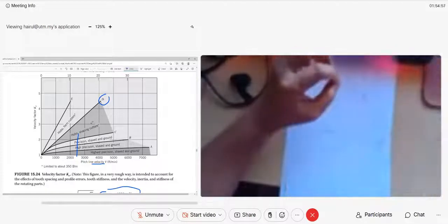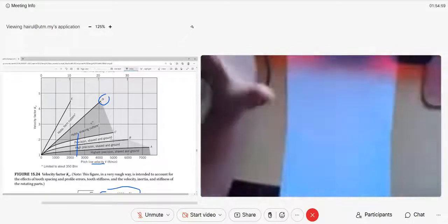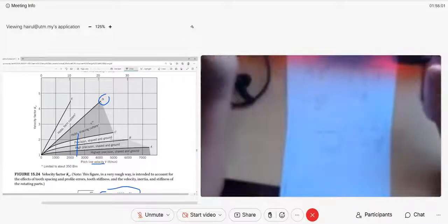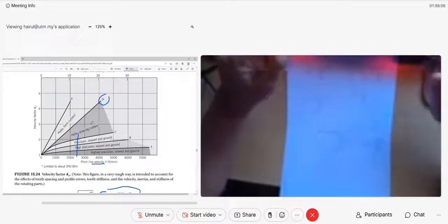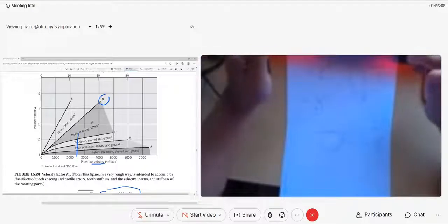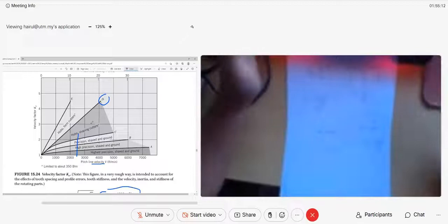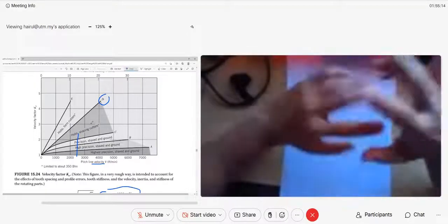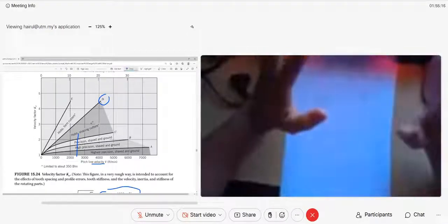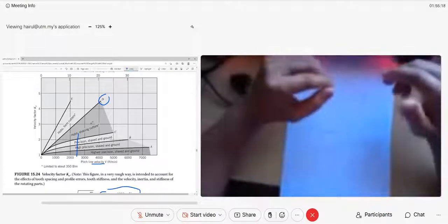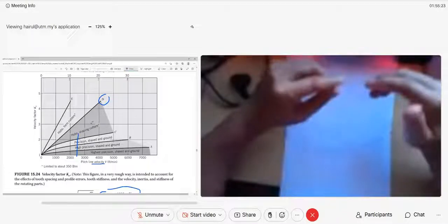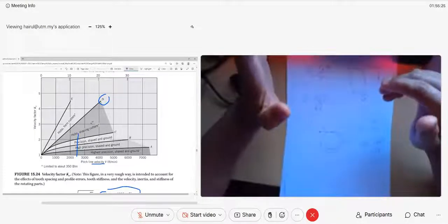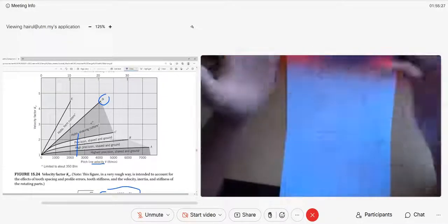Let's say you and your group assume that the drum of your foot mixer, for example the food technologists from Nestle, your client, need it to be accurate at 60 RPM. You justify that in your report and put it into a real situation, because this is like engineering consultancy work. So you must be accurate, so you use spur gear instead of V-belt.